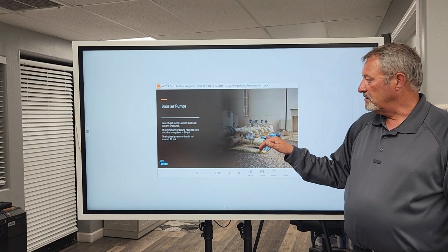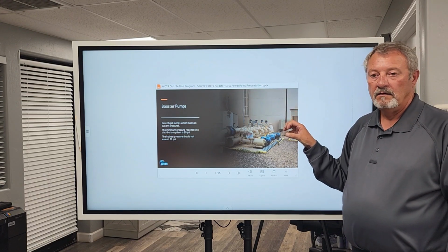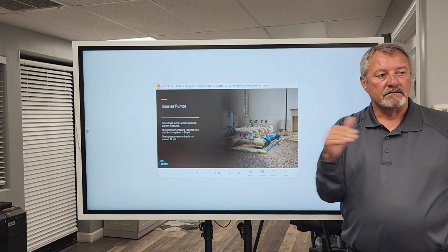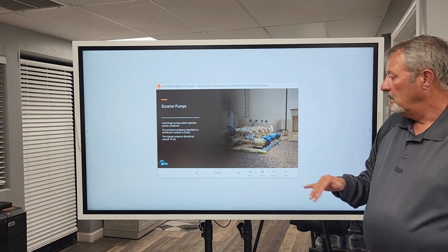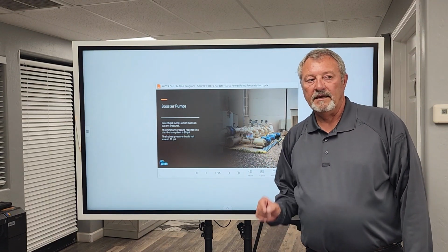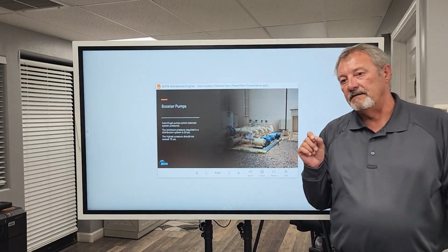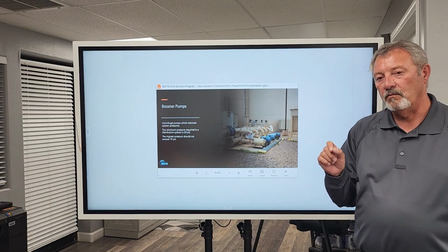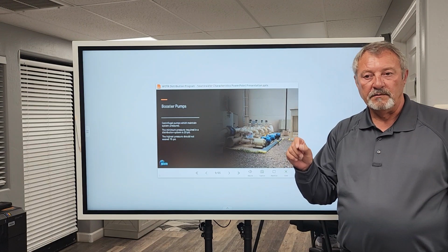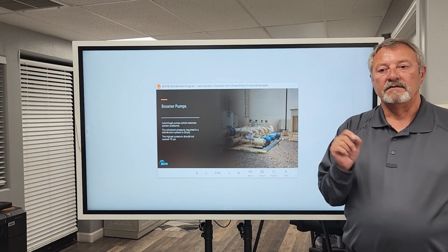The booster pump station is the point where it pulls water from the ground storage tank and pushes it into the distribution system, which sends the water to our customers. We call this point the EPDS, the entry point to the distribution system. It's important to understand that this is a point where the water treatment and storage ends, and it's the beginning of the distribution system.